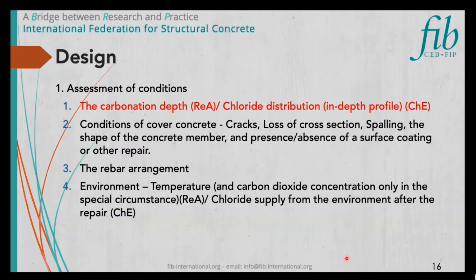The rebar arrangement must be specified for the circuit design, such as connection points between the rebar and the lead wires, the number of connections, the DC power supply capacity, the number of power supplies, and so on. In addition, the presence of prestressing tendons must be checked. Environment is an important factor as it affects the redeterioration after the treatment.